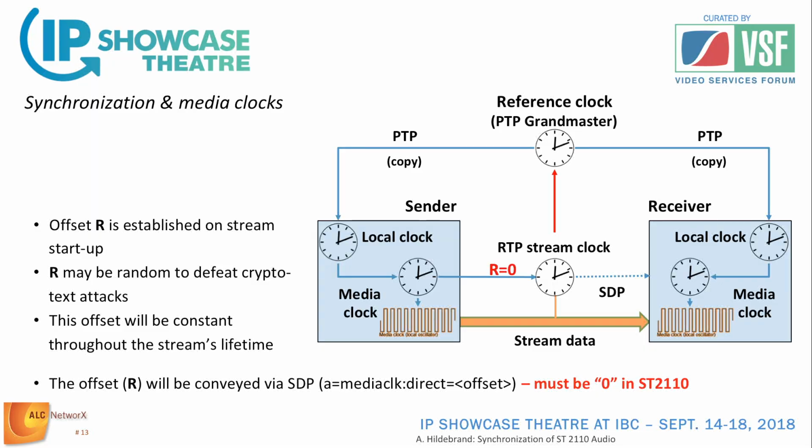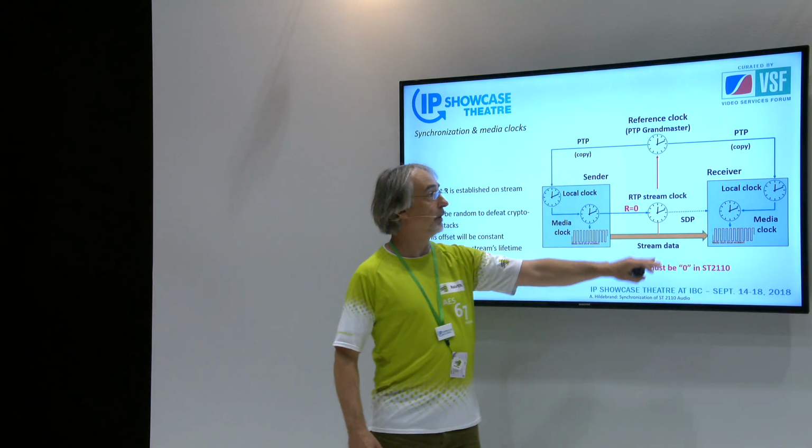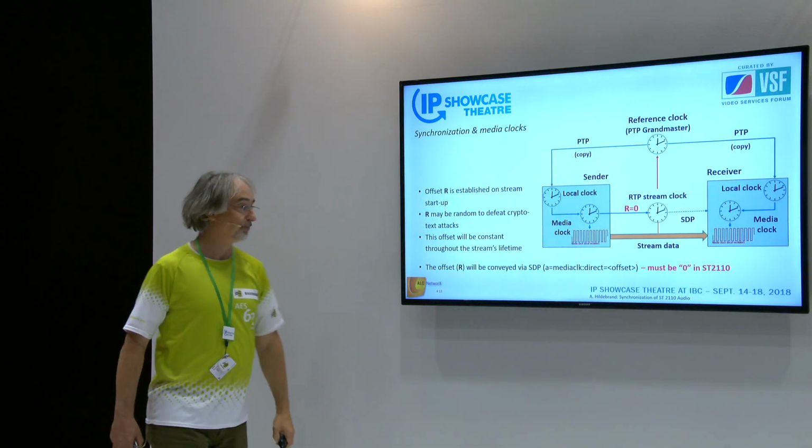So we have three different clocks: the wall clock, with the local clock, the media clock, and from the media clock we have stream clocks. Within ST 2110-30, all these clocks are fully running in sync, and any stream fully relates back to the master clock time.